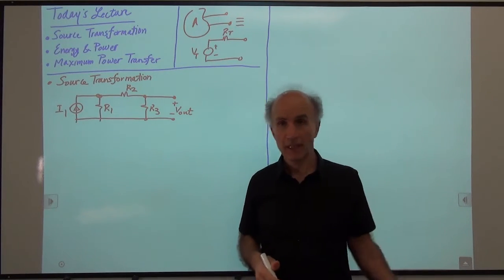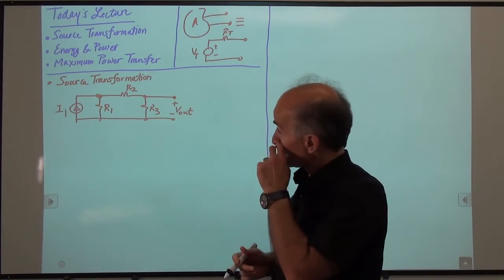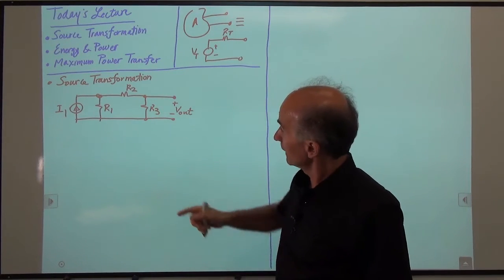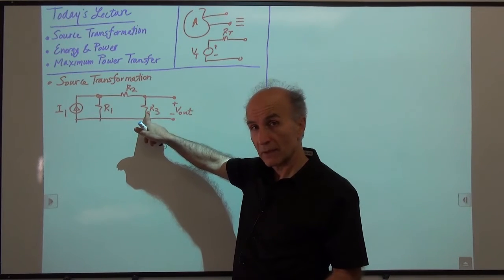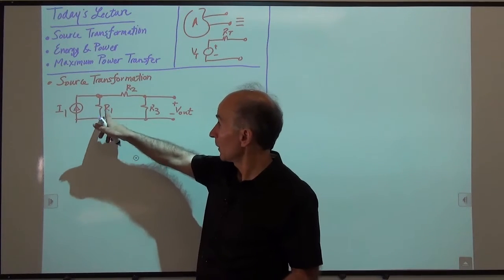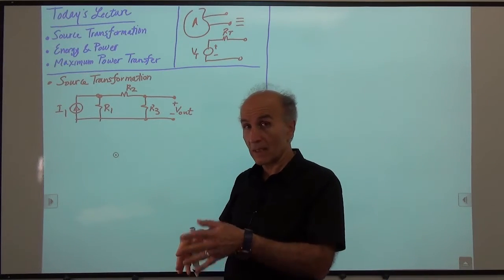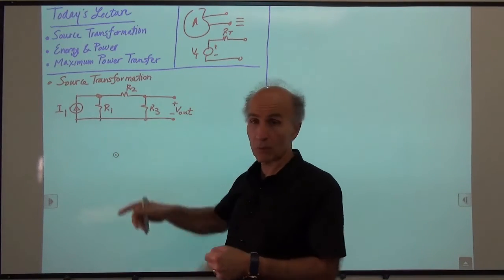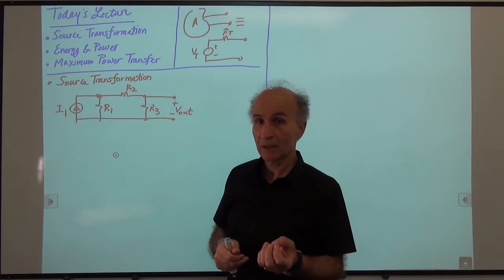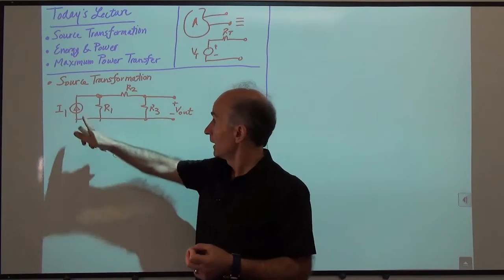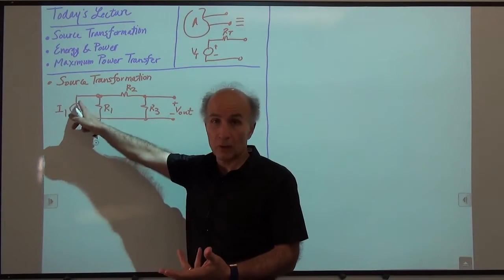You can use node analysis, mesh analysis, Thevenin's theorem, Norton's theorem, whatever you want. But also, if we just look at the circuit, we see that this resistor and this resistor are in series, forming a voltage divider. So we're thinking, if we also reduce this to something else that had a series resistance, that series resistance and this would all be in series, so the circuit would be simpler to analyze. So that tells us that perhaps we should replace this combination with a Thevenin equivalent. This looks like a Norton equivalent, right?